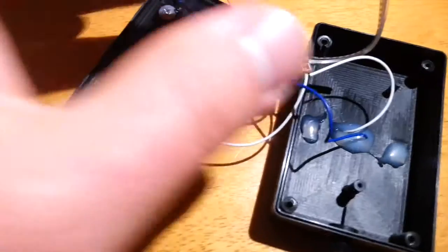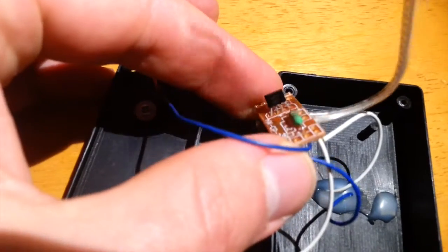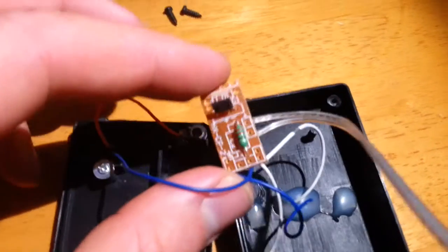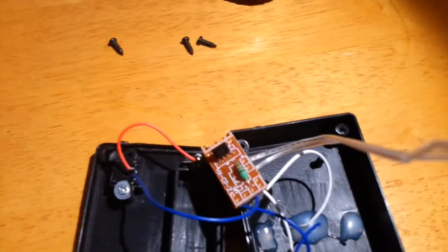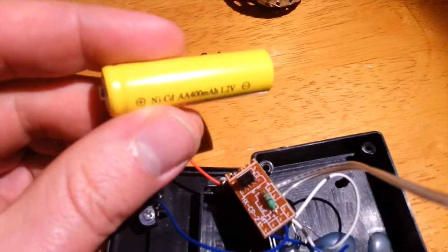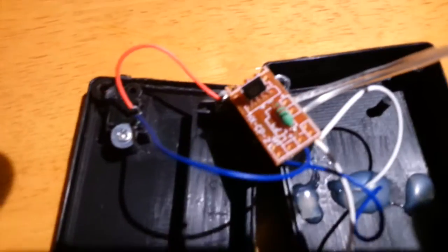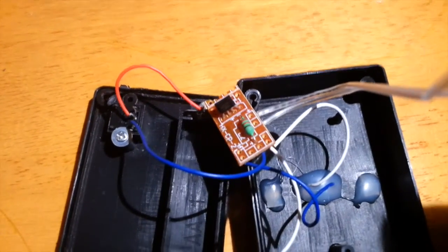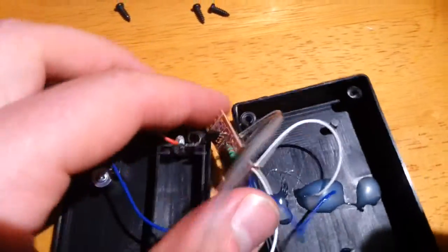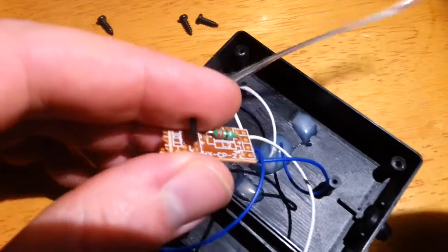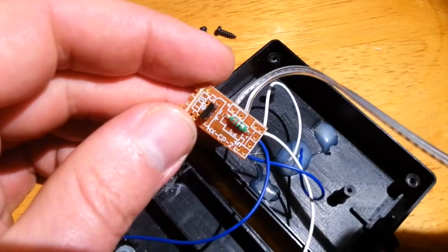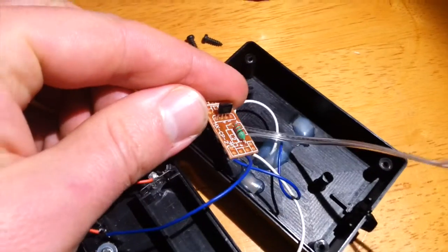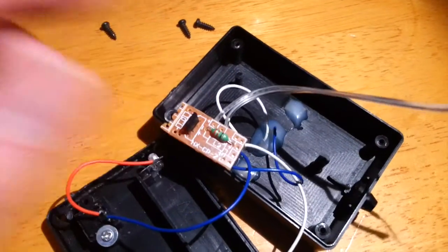Here's a close-up view of the circuit board, and there's the little 4-pin chip that's really common in these solar garden lights, and an inductor. Together they boost the 1.2 volts nominal from the nickel cadmium cell up to 3 volts or a bit more in order to light the LEDs and reach their 3 volt forward voltage. There's provision on this circuit board for capacitors and all sorts of other, no doubt, useful components, but they've gone the minimalist route here and have nothing more than the 4-pin IC and an inductor. Nevertheless, it seems to work.